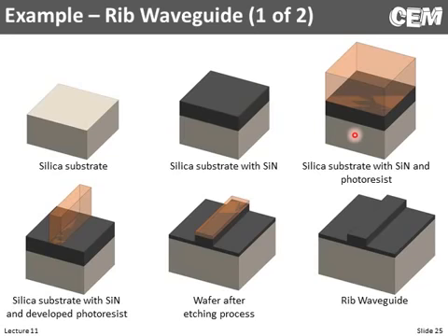Now here's where we put it on a spinner, and it spins at several thousand RPM, and we pour something on it that pours like pancake syrup that we call a photoresist. And it's spinning so that it spreads itself out evenly over the spinning wafer, we call it. Then we do a process where we put a mask over this that will shadow certain regions. So let's say it shadows the center region, and we expose it to light. Now, where the light did not get absorbed, the resist will wash away in a developer solution. So we develop it, and we're left with a standing portion of our resist.